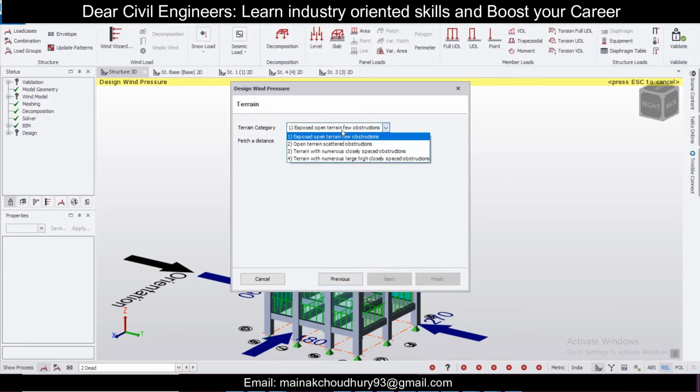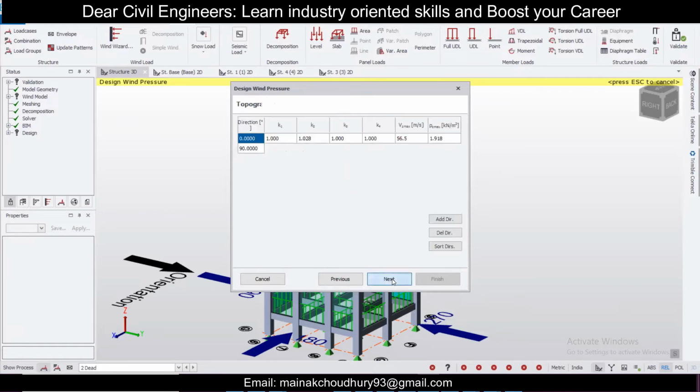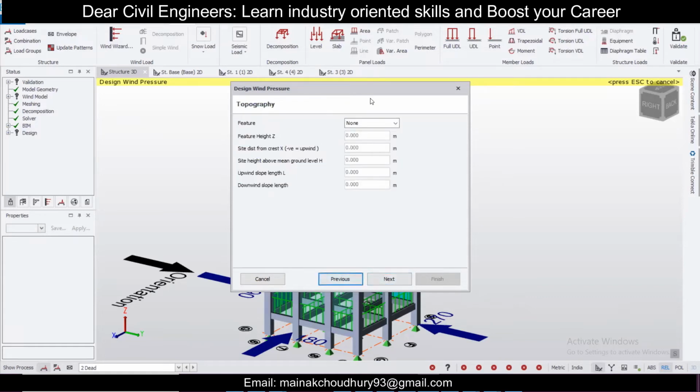Just click on next, and the terrain category will be exposed terrain with few obstructions and terrain with numerous closed obstructions. So we're going to go with open terrain with scattered obstructions. Fetch distance is basically the distance where the wind patterns are the same. So I'm going to go with 5 meters. For this topography feature, you can take any topography feature, or you can also ignore this. If you want to ignore this, just consider none. Generally you can ignore this, so just click on none here, and then next.